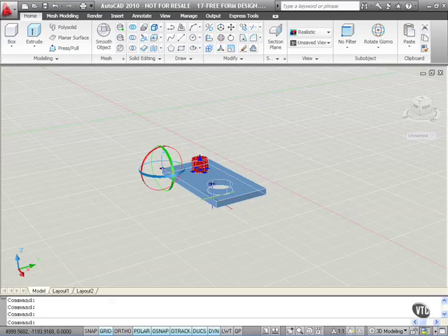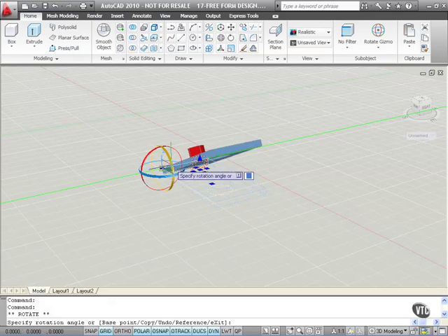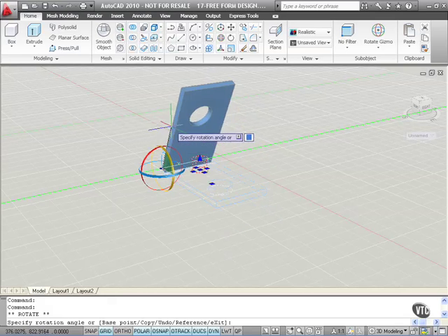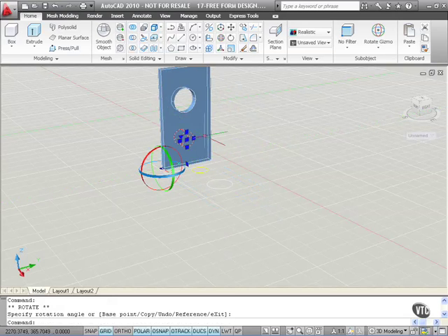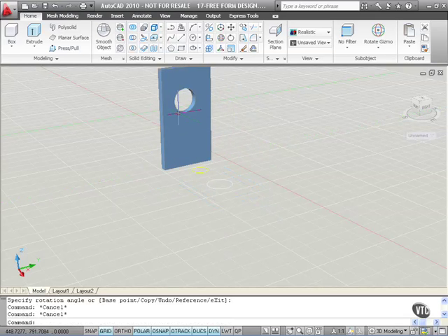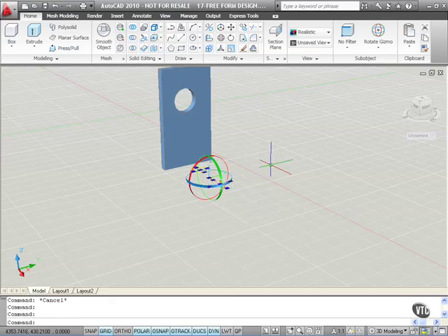And now what I want to do is rotate this using the X-axis, the green. Can you see the green axis appears across the screen there? And if I click on that line, I can now rotate about that axis. So I can take that up there like that, vertically to there, left click, hit escape to deselect, and look, it's now changed the rotation. The two circles have stayed there, but I don't need those anymore now. Notice the gizmo appears again on those as well. I hit delete there. I don't need those anymore.